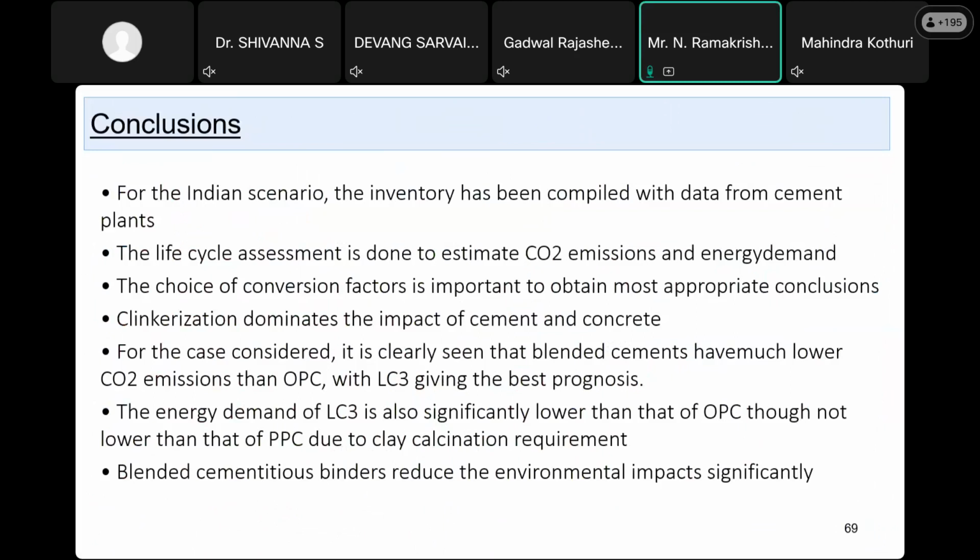So what happens is the cement industry being a contributor to greenhouse gases and carbon emission, there is a pressing priority to work on the reduction of carbon footprints to ensure sustainable development. In addition to the reduction of the carbon emissions, reducing the clinker to cement ratio by the replacement, and using blended cement will improve the quality and long-term performance of concrete.